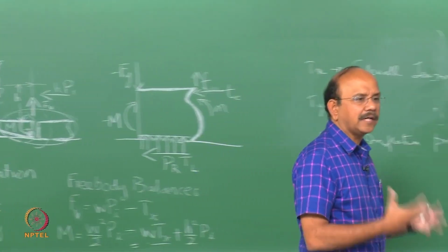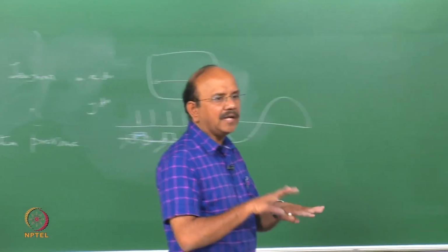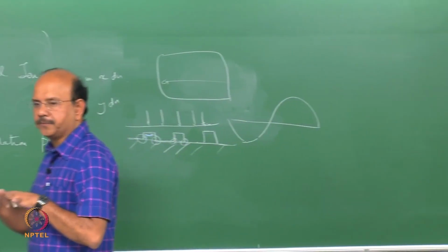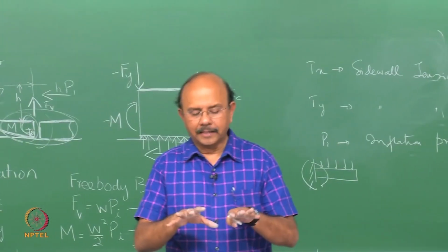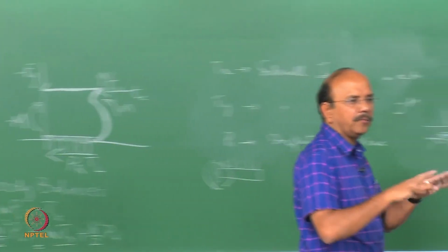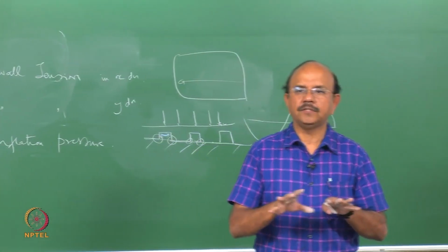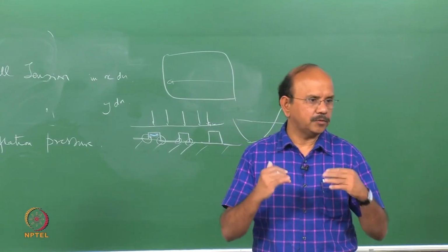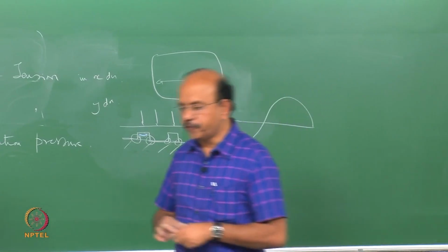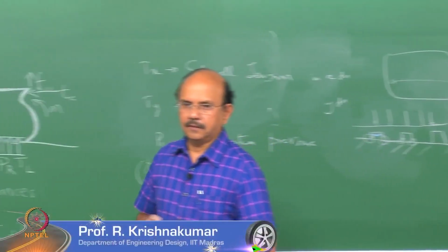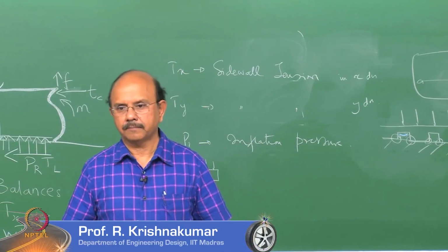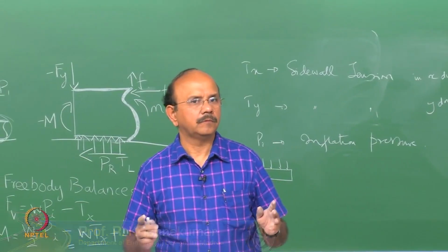The contact patch is also affected by the uneven distribution of longitudinal forces between the various ribs, and the contact patch tends to adjust itself so that the strain energy as a system is brought to a minimum. So there's a small rotation. That's as far as free rolling is concerned. We will look at braking and then go to the contact patch in the next class. Right? We'll stop here.